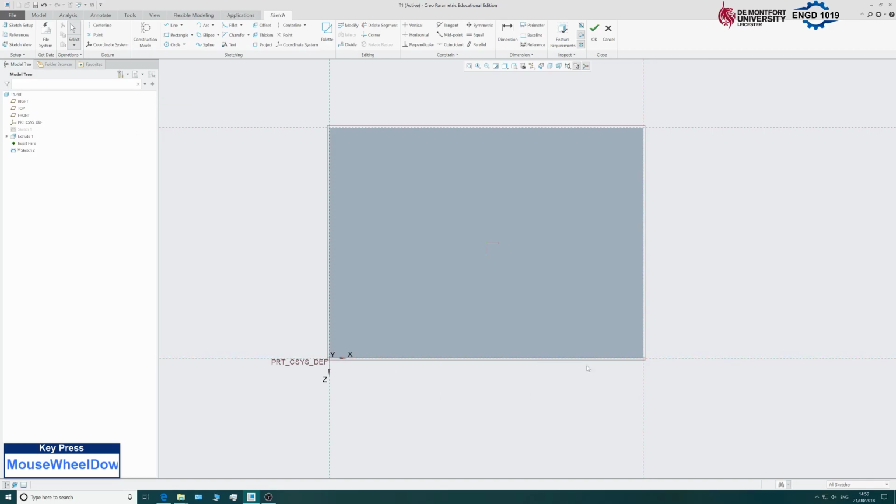So what I'm going to do is, first of all, draw this cutout section along the bottom here. And to do that, I'm going to use the line tool. So if I click on this line tool, again you'll notice the cursor's changed, and this is what I mean by these lines, being able to snap to them. So I can snap to these points.